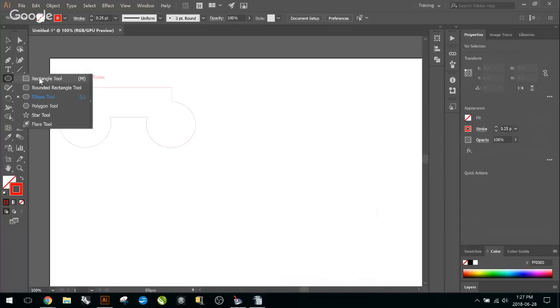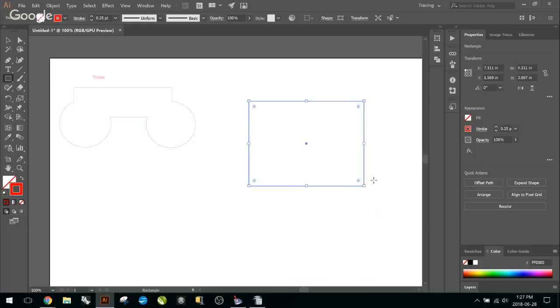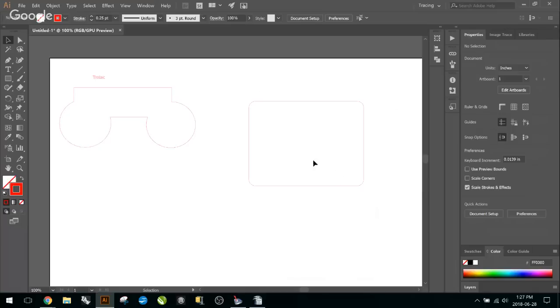So if you select your square shape here, you can drop your shape. And now with your selection tool, you'll see these little dots in the corner here. You can select one or more if you hold the shift button. And you can drag these, and you can actually make rounded corners now. So this is all customizable. You can see here as I'm dragging this, these numbers up here are changing. So if you needed an exact corner, I know a lot of people use 0.25 here. We'll use 0.25 of an inch for a corner here. And now all your corners should change. Perfect.